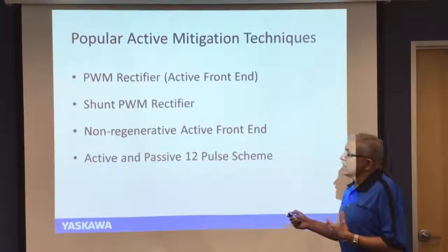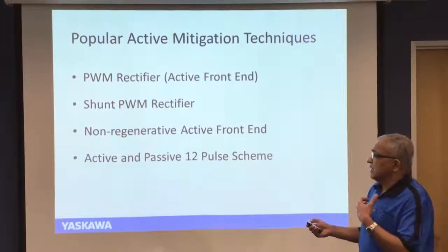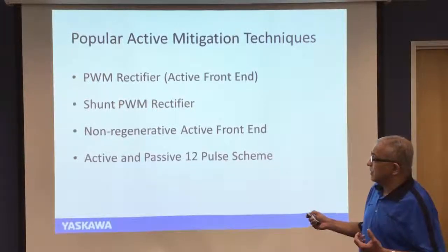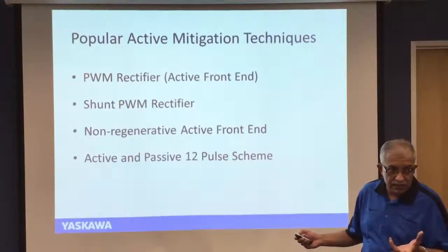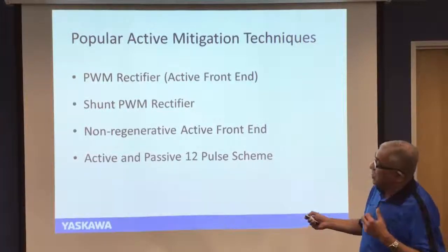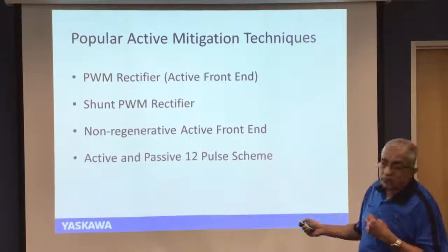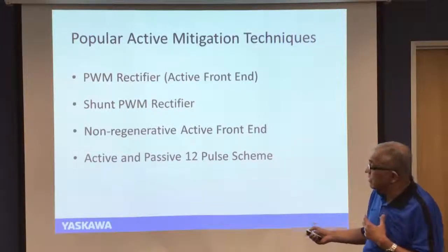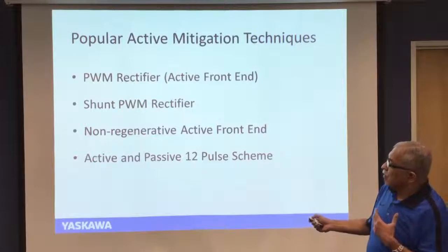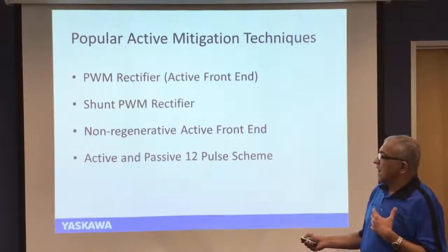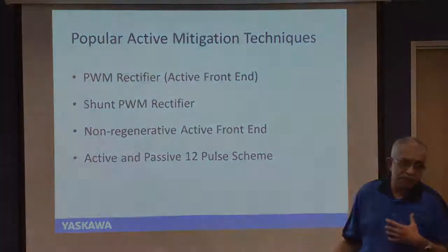Some popular techniques used in the industry are active techniques, active front-end rectifiers. We'll discuss the active front-end topology and how it influences the system cost as well as its performance. Then we have the shunt active PWM rectifier, which is a variation of the PWM rectifier. And then we have the non-regenerative active front-end rectifiers. And I'll also discuss the active and passive 12-pulse schemes.